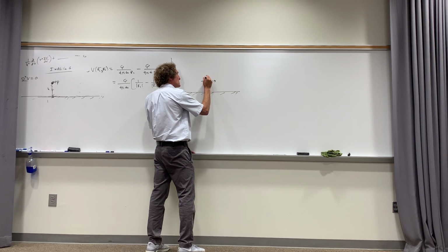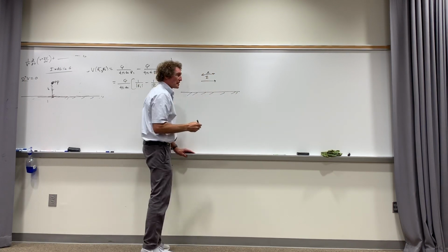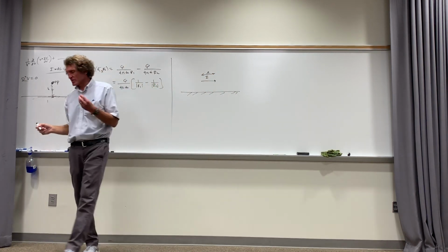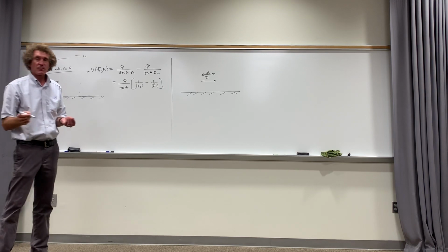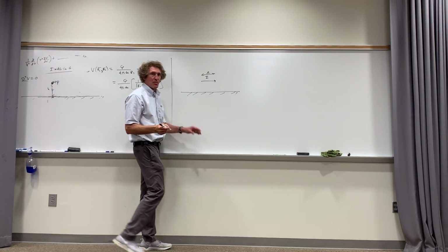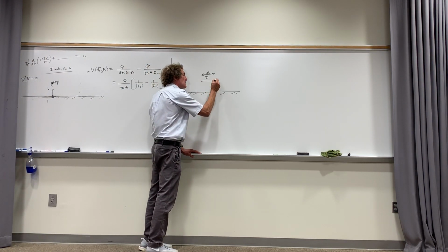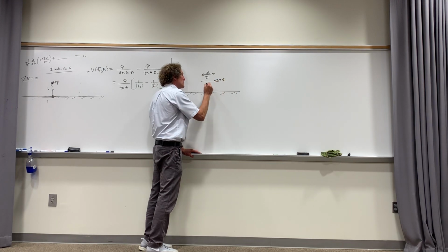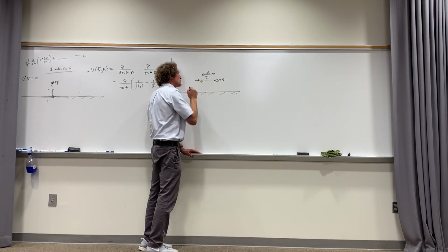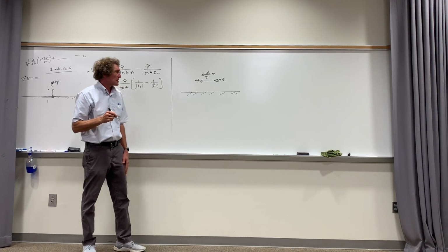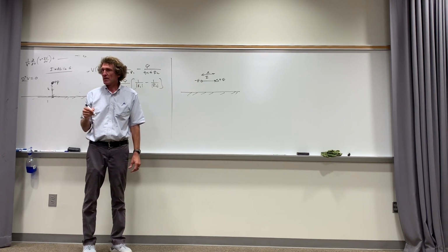And we're going to assume this has a current I, and it has a length L. Right? Now think about this just as a segment of current. What happens when current flows? If we had a short dipole there, y'all realize that positive charge would accumulate, and it would create negative charge or a lack of positive charge there. Do y'all agree with that?